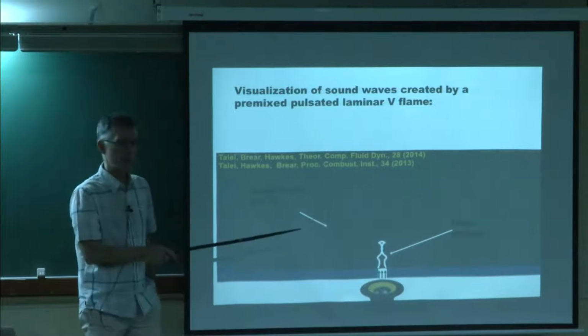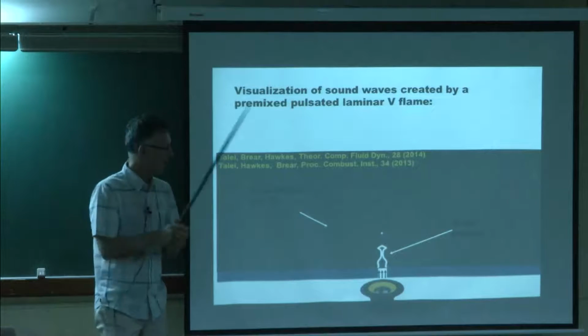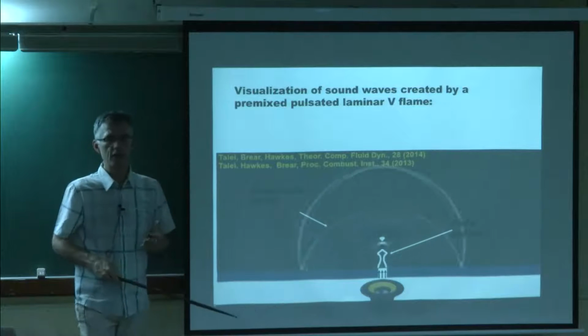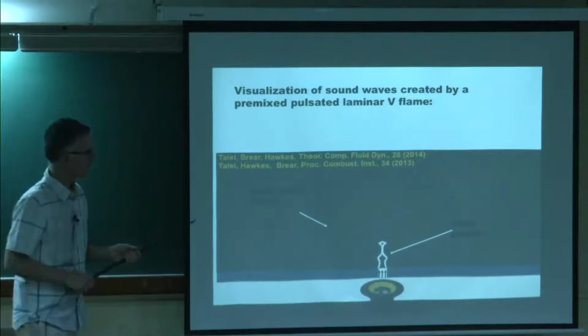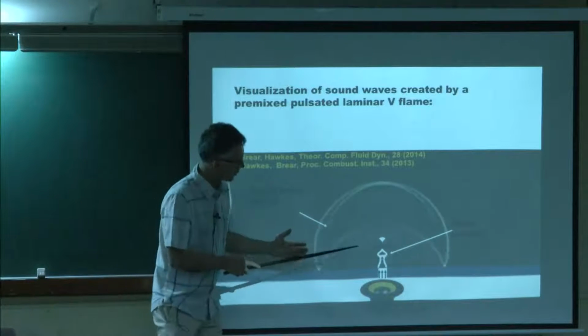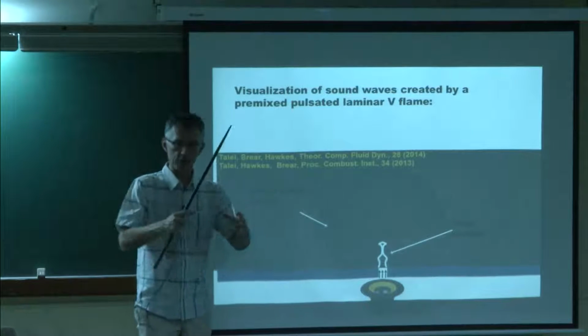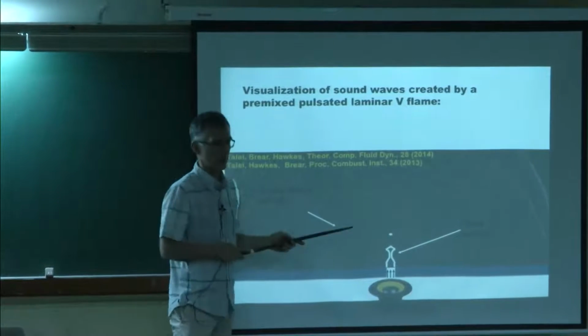What happened here is we had a big change in heat release because a pocket disappeared. And when this pocket disappears, look at the pressure wave it is sending. This is why we keep calling those flames monopoles, because the emission really looks like a monopole acoustic source. It's like a loudspeaker, if you want. It produces sound. Every time you have dq/dt, you have a wave.